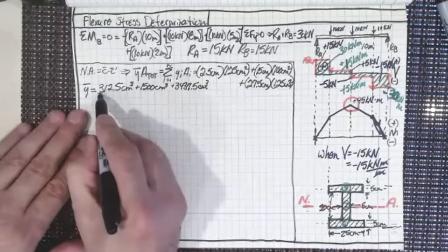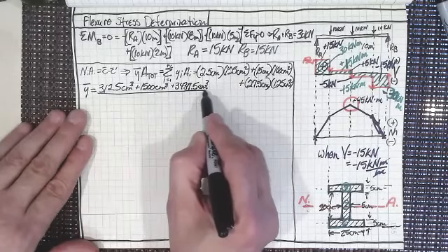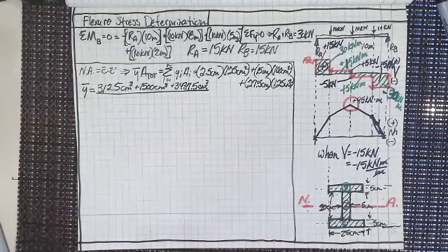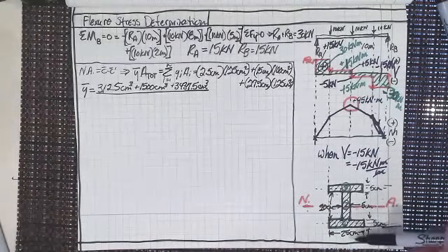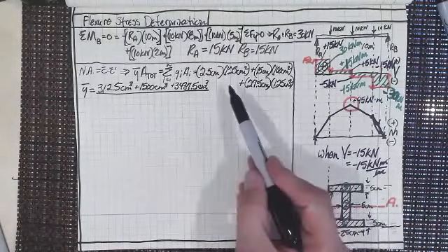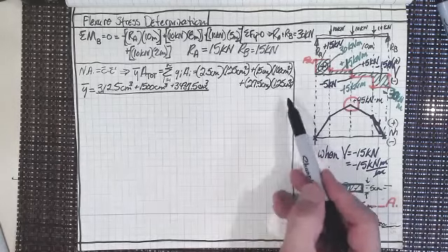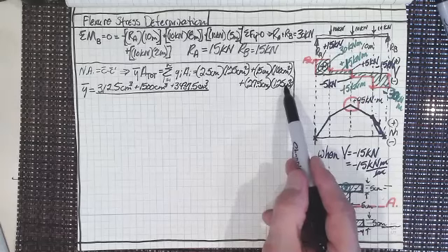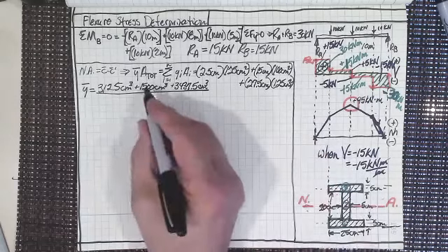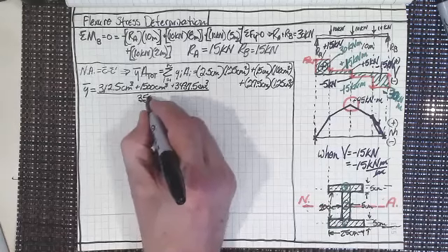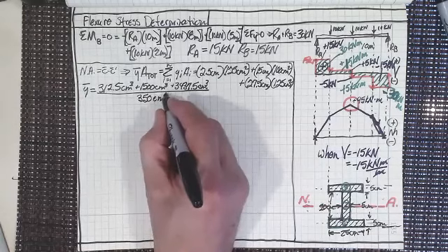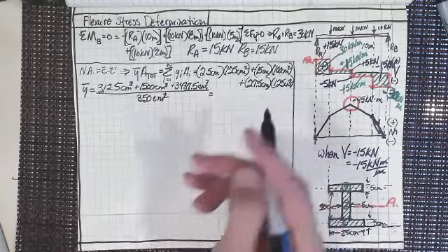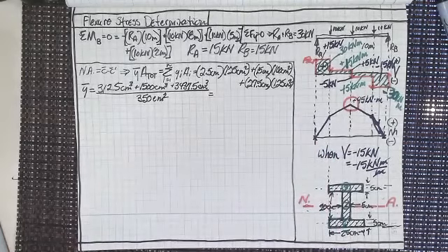And we want to divide that by the total cross-sectional area. Now let's just do this. We've already done it. 125, 100, 125. 125 plus 125, 250. Plus 100, 350. So we've got it divided by 350 square centimeters. And so what this gives us is y bar, and I hope y bar comes out to 15.